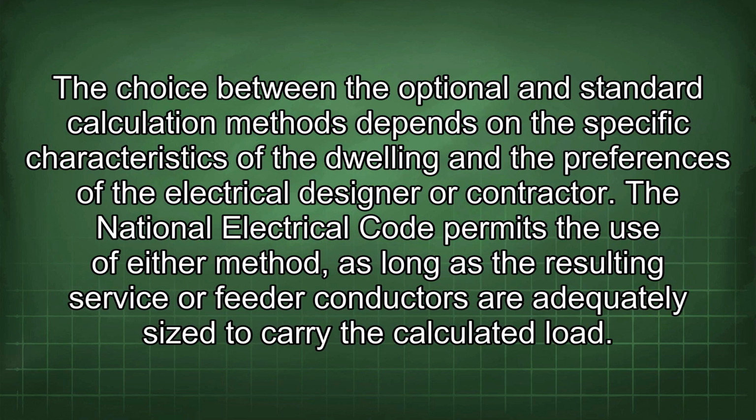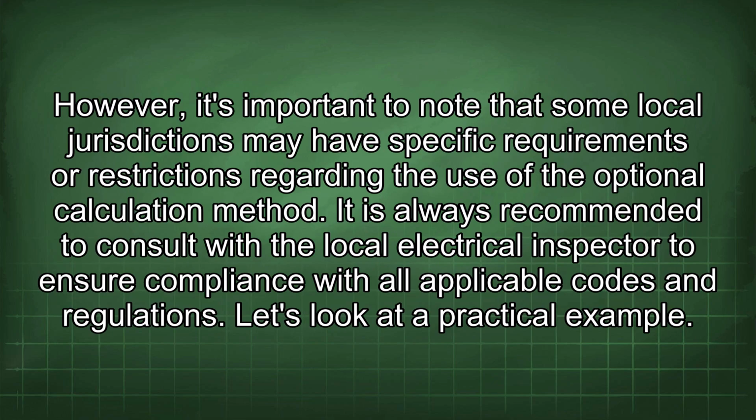The choice between the optional and standard calculation methods depends on the specific characteristics of the dwelling and the preferences of the electrical designer or contractor. The National Electrical Code permits the use of either method, as long as the resulting service or feeder conductors are adequately sized to carry the calculated load. However, it's important to note that some local jurisdictions may have specific requirements or restrictions regarding the use of the optional calculation method. It is always recommended to consult with the local electrical inspector to ensure compliance with all applicable codes and regulations. Let's look at a practical example.